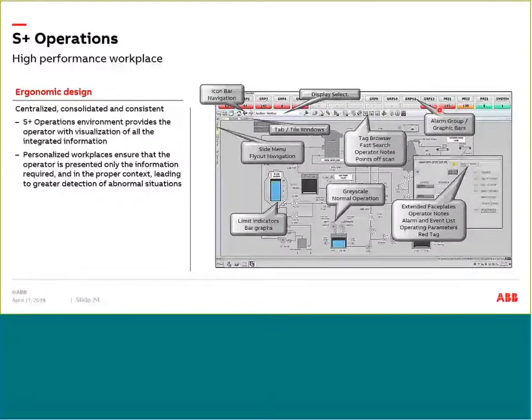So immediately when an operator looks at this, my eyes are going to go to the red and say, I need to sort out the red because that's my priority 1 alarms. And then I can move to the orange and then to the green. Of course, it depends on the alarm management strategy that you have at your site.